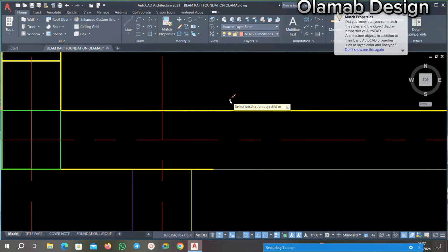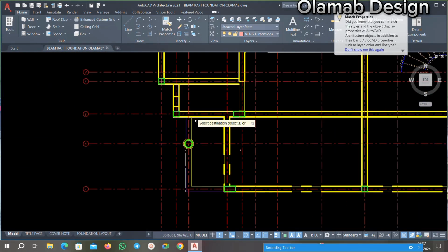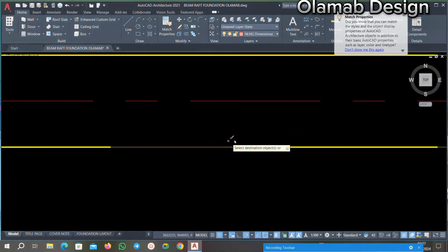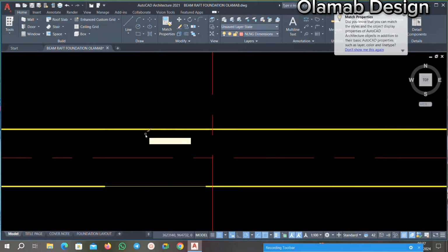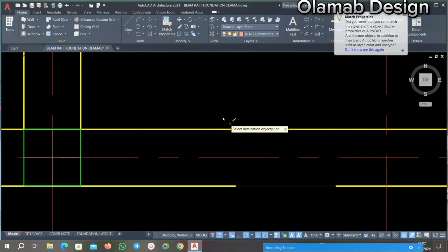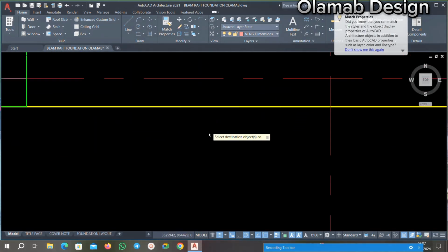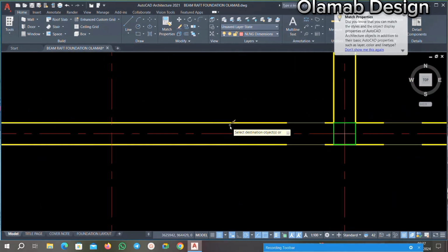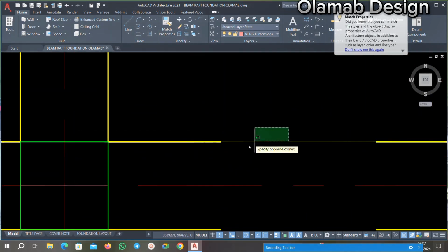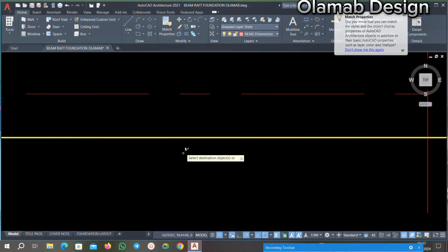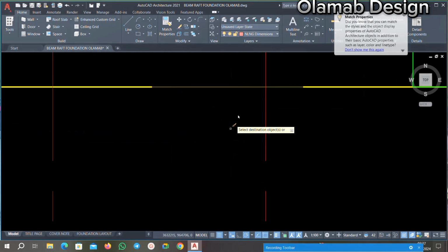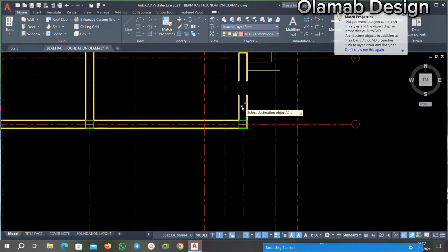No matter what, try to do your general arrangement. Some people look at the structure and go straight to Prota Structure. If you are working in AutoCAD first, you will be able to see all your errors carefully. That's why I'm also taking my time to teach you more on general arrangement.